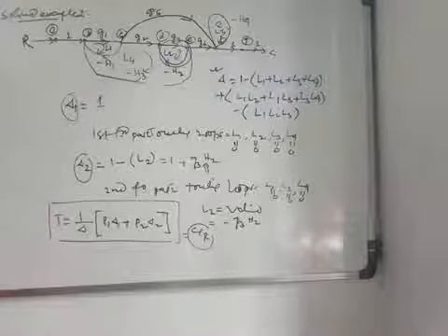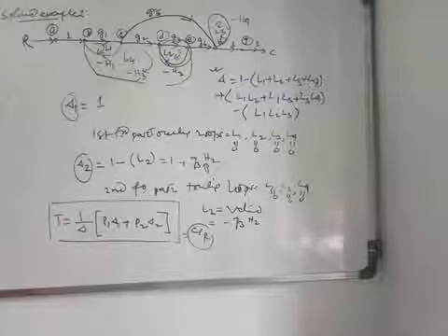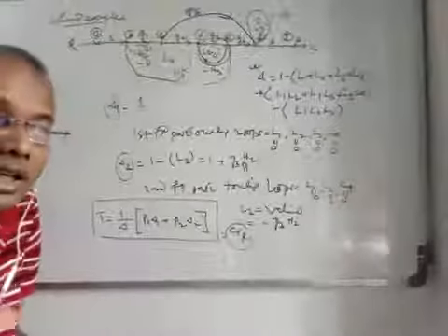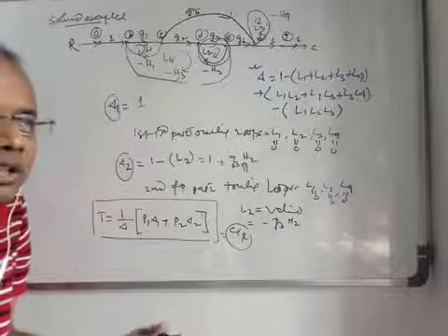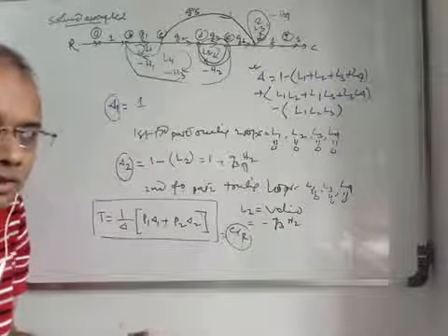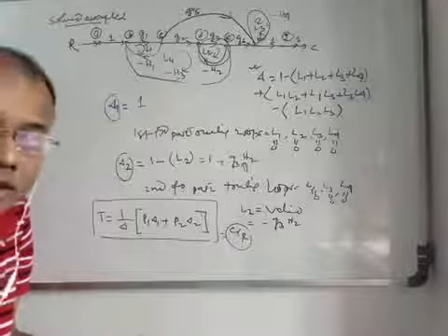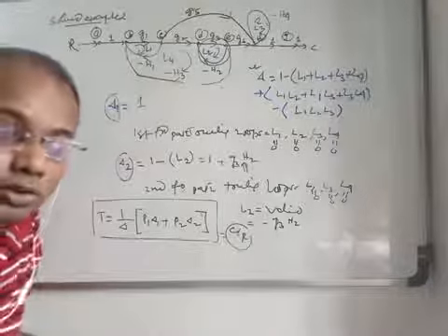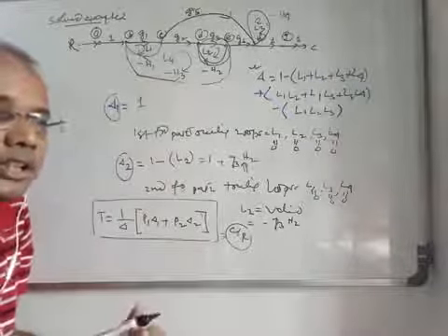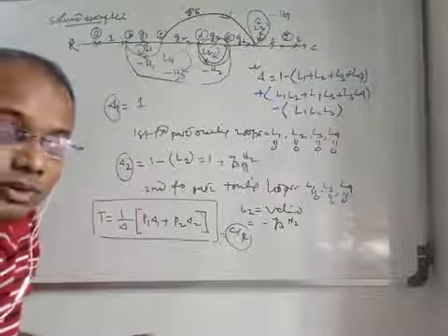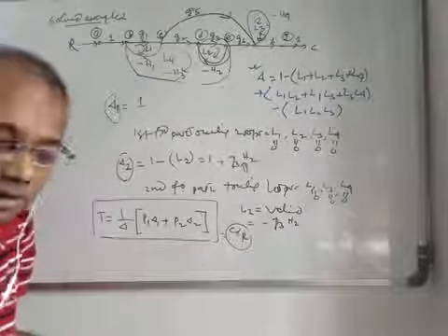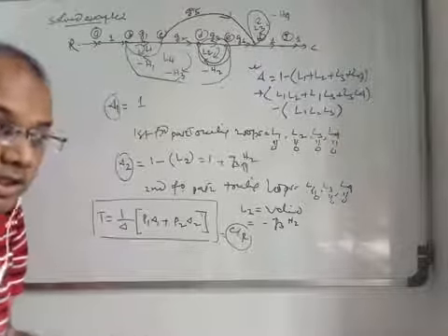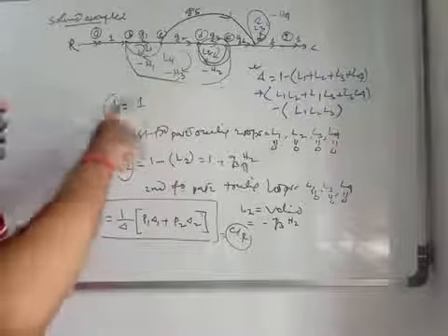So what you have learned is how to find out the different path gains, how to find out the different forward paths, and next the different individual loops, and whether the loops are formed. There may be two possible combinations of non-touching loops, that means whether they are sharing any common node or not, and if there is any possible combination of three non-touching loops, that means three different loops which are not in touch with any common node. And finally the value of delta.